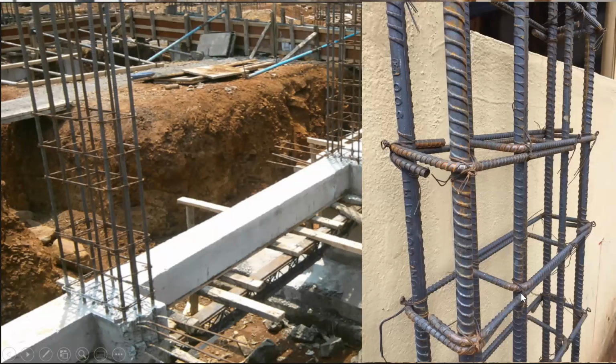So we'll try to see this again. There's one more bar. Let us say 1, 2, 3, 4, 5, 6. There are eight longitudinal bars. So this one lateral tie will connect all the bars. This is the main bar. We call this the master ring. The other lateral tie is connected to the inner 4 reinforcement bars. So this is connected to 1, 2, 3, and 4. And the outer one is called the master ring that is connected here. So this is how it is.